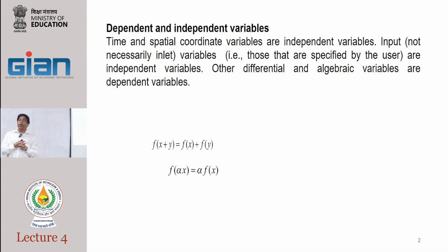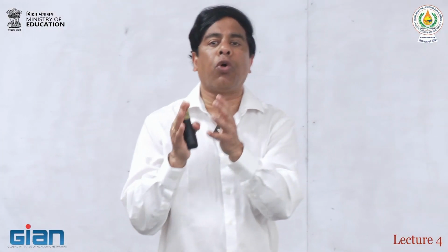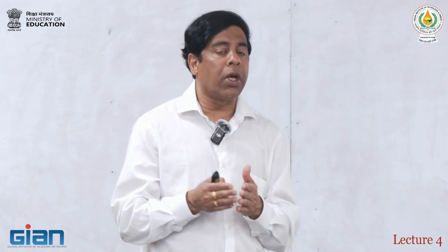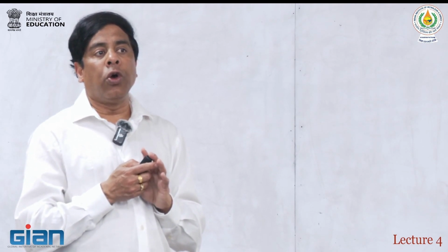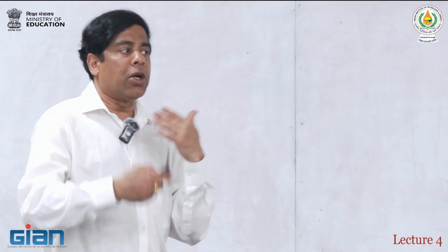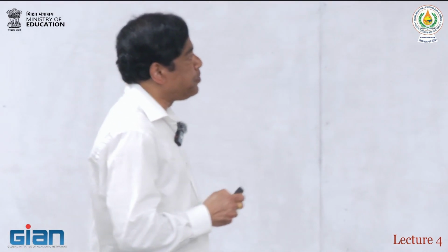So it is not. But the pressure at the boundary is an independent variable because that is coming from somewhere else. If I want to raise the pressure, I have to put in a compressor or a blower or something, but the pressure at the boundary becomes an independent variable, which I'm saying is coming at that pressure, but the flow rate is not. So you have to be careful in terms of what you specify. And tomorrow and the day after, you will see that we will be discussing this more.